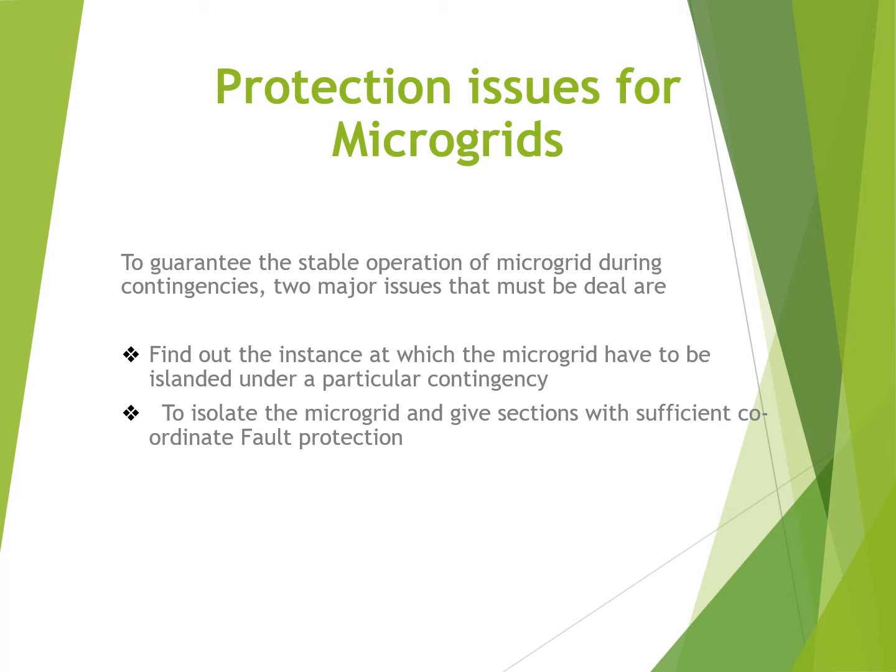When we change from grid-connected control to islanded or standalone mode, there will be a clear reduction in microgrid fault level. So the operation and sensitivity of some relays may be affected, and rapid islanding during non-fault situations can mainly be achieved if we install high-speed communication channels between these two grids, that is, utility and microgrid.